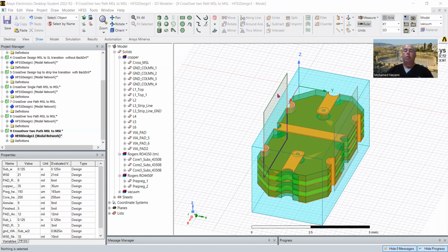So that has to be designed carefully, since we're doing a lot of stuff at millimeter waves, X-band. Down in the S-band, L-band, maybe one could just punch a via and transition down to a lower stripline and then go back up. It doesn't have to be super duper designed, but carefully laid out.